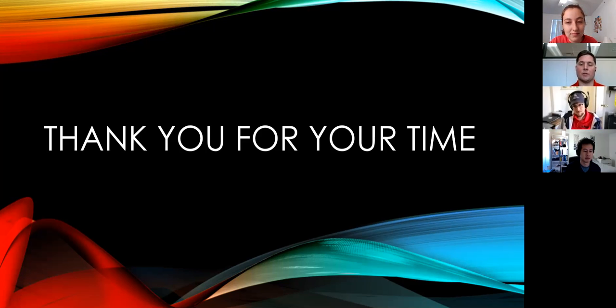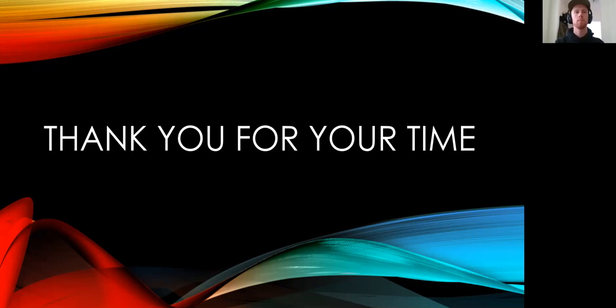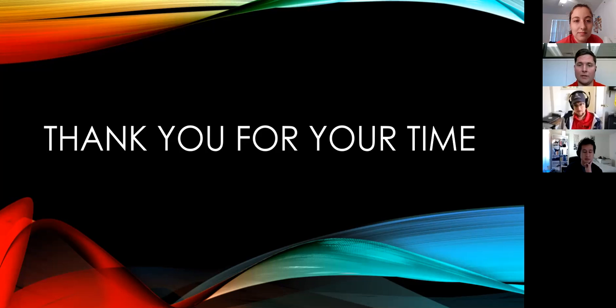That's a great question, Henry. We actually have a white paper on 2D versus 3D metrology. So industry standard would be a profilometer trace. And that's literally a 2D trace across the surface of the lens, which is just a sliver. That's what's standard. You can request 3D data. We have a 3D measuring device for aspheres, and so we can provide that.